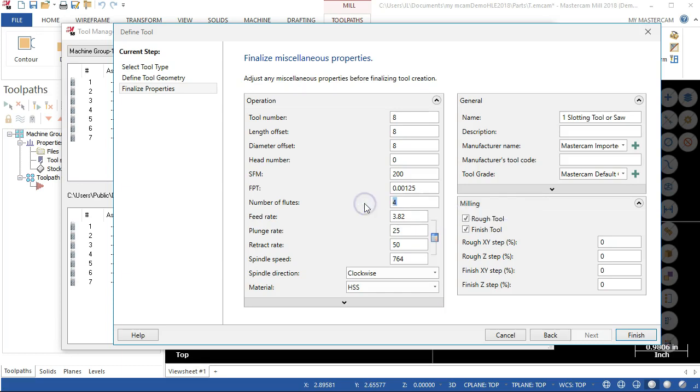Now this one's showing 8 flute as a staggered cut. And then the spindle speed, yeah, let's start with the 1000 RPM, see what that does. That bumps it up a little bit. And if we don't get too crazy with the engagement, I still don't want to get too aggressive with that feed in, feed out.